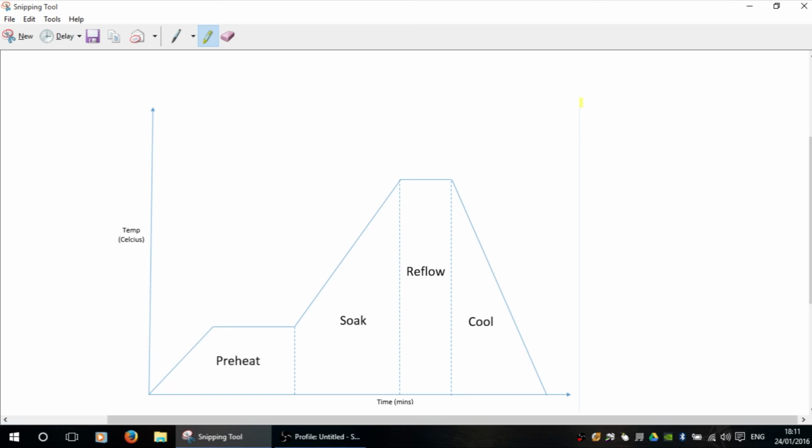Profiles can be very, very different for the following reasons. I'm not just telling you this to make it seem awkward and harder than it is. These are real, legitimate reasons for having to build your own profile on your own machine. One of those reasons is your actual location and where your machine is. The ambient temperature of your room, for example, where your rework station sits, can have an effect on your profile.